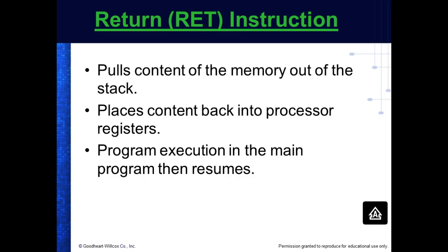When it runs the subroutine, it's going to use those same registers, right? It might use the flag register, accumulators, anything else that's capable. Then when it gets through there, it pulls all the old information off. So if you have something in a subroutine that was affected by the previous instruction, you better save that so you can access it from the main program. Does that make sense?